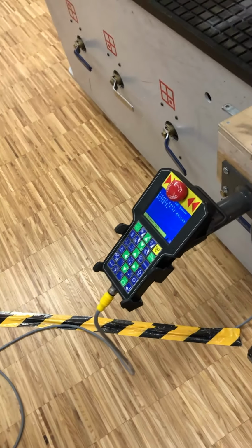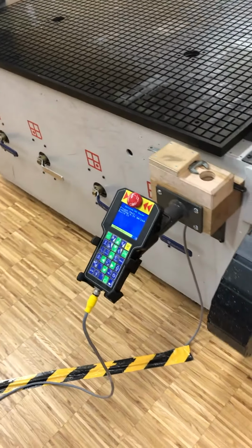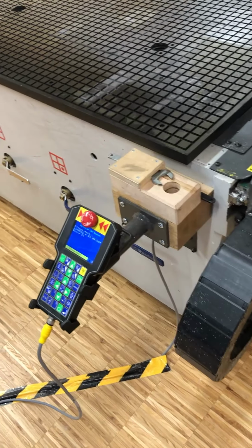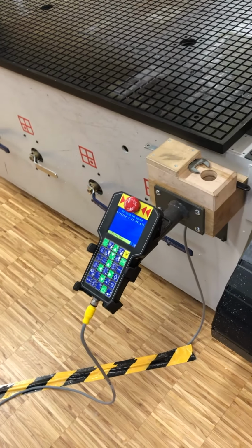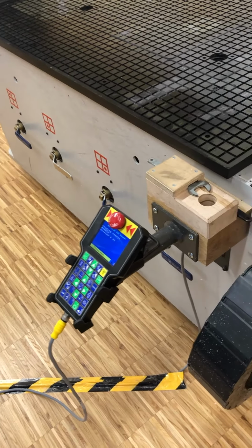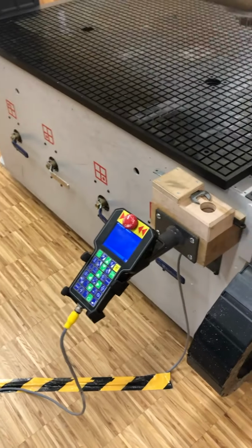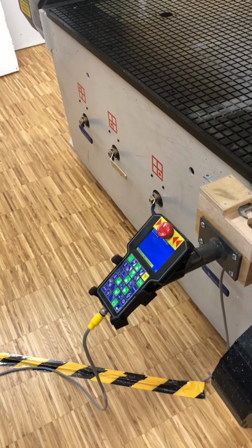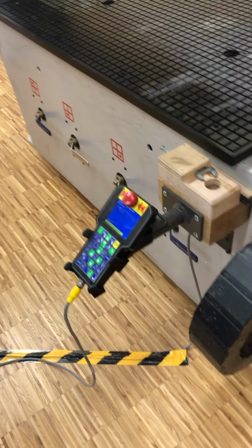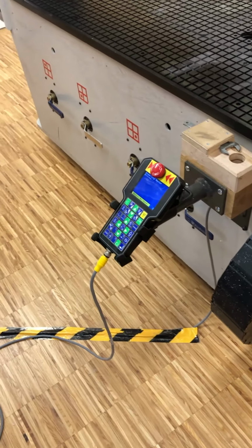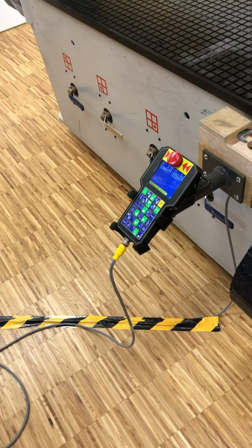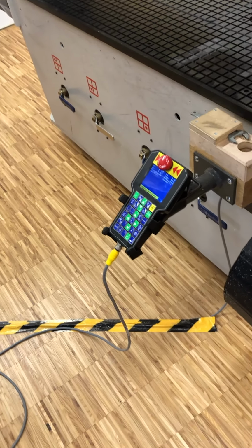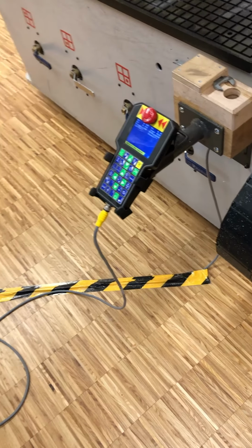Alright, now we can see how it boots up, and it loads the firmware, I guess, and then it loads a software, I don't know if it's called a plugin in this case, which is called an automatic tool changer. And for this introduction we will not go into the automatic tool changer, but just so you know, in Fusion 360 you can define several tool paths with different tools, and it can automatically change. So you only need to supervise it, but you won't need to complete one tool set and then manually change.